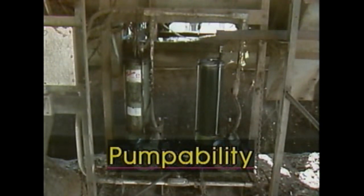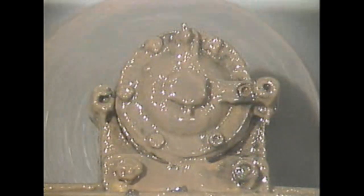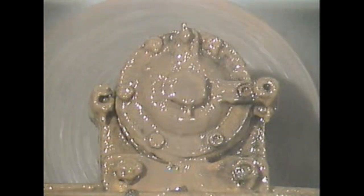If a grease must be pumped through a centralized greasing system, the grease's pumpability should be considered. Pumpability is a measure of how easily a grease can be moved or pumped through a centralized greasing system without clogging the pipes or the components in the system. The water resistance of a grease is an important property if the grease will be used with machinery that can be damaged by water. Many greases break down or dissolve when they come in contact with water, but most greases that contain thickeners such as calcium or lithium soap, which are insoluble in water, resist water very well.